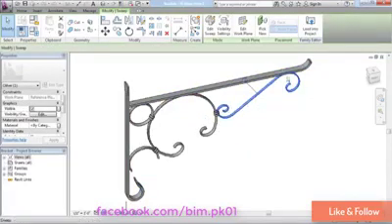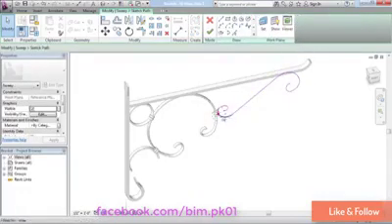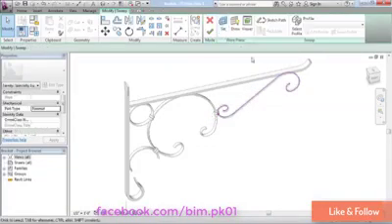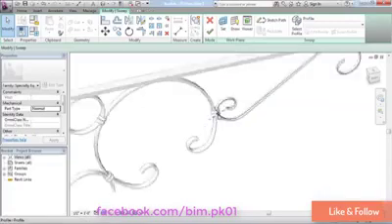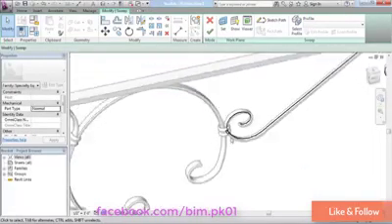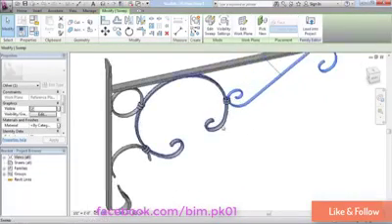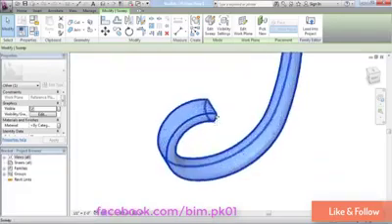So it's just a curly shape here for the path. If I edit that sweep, you can see there's the path right there. And this green line is where the profile was sketched, and that profile shape is, if I zoom in there, just a small rectangle. Pretty straightforward shape there, but makes for a nice effect when it's done. This is also a sweep, a little more complex. It's got a little bit of a curved shape to it.